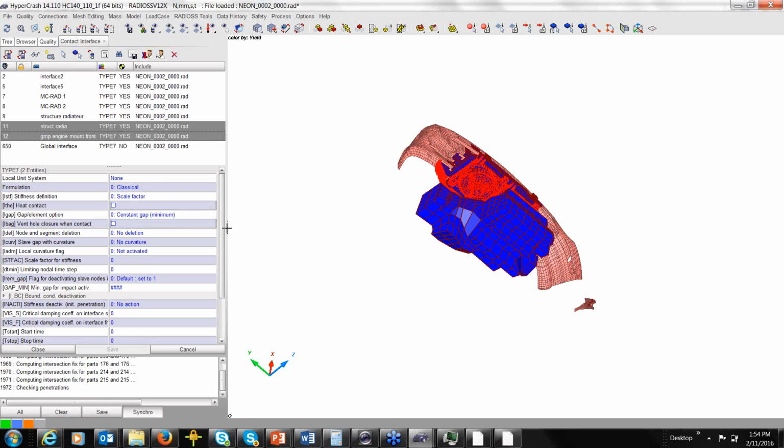Another question in crash analysis: if we use SPH, what should we be careful of? Okay. In the crash analysis, first of all, you have to know where you use the SPH in the crash model. The crash model where I can foresee the SPH is in your fuel tank sloshing. If you are concerned about fuel tank sloshing, remember on one of our slides up here, I show you.